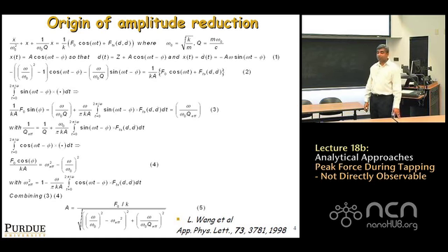So when you combine the two things, equations 3 and 4 together, you get a very nice expression for what is the amplitude, steady state amplitude, in terms of omegas and so on. The reason it's nice is, if you go back a few lectures, we did the transfer function of a cantilever driven by a force, right? Simple harmonic oscillator, what the transfer function is, what the amplitude and phase is, it takes the same form. This is the same form as a standard transfer function of a cantilever that's forced. And if you want to know how its amplitude changes with drive frequency, this is the same expression, except in the denominator, you've got omega effective and Q effective now, which include in it tip sample interaction forces.